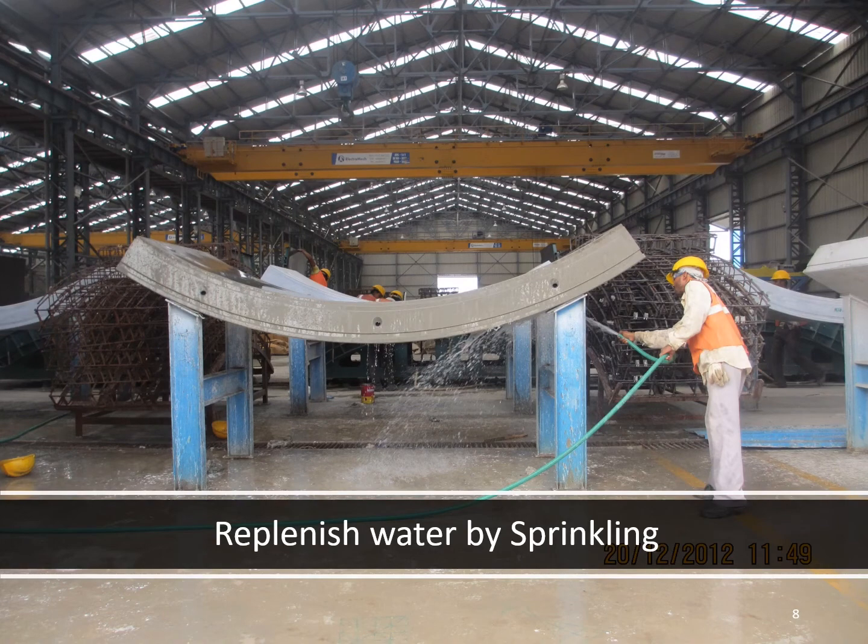Similarly, for replenishing water by sprinkling, wherever water comes into the picture, the temperature of the water is important. Whether it is sprinkling or ponding or immersion, in all cases the temperature of water is important when you are doing curing with water. If you are able to maintain the temperature of the water, you can continue curing with water. If you are not able to, it is better to change your curing methodology to other methods where the temperature restriction is not required, and then you can have your conventional method of curing.